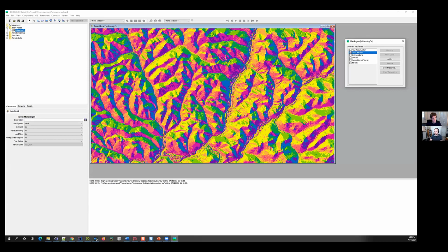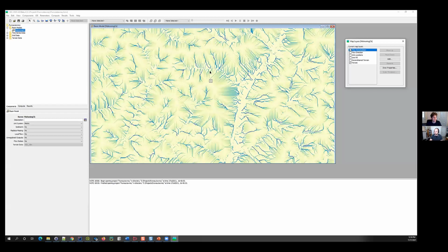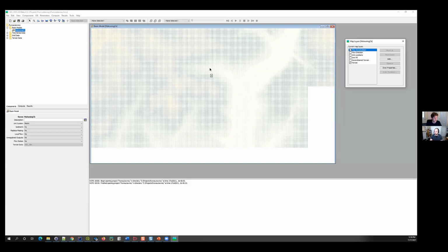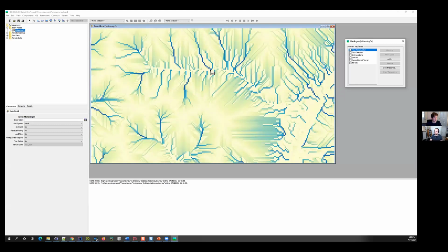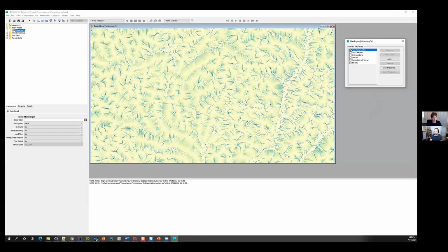And then if I look at the flow accumulation grid, it gives a notion of how many cells upstream of a particular cell flow to a given cell. So if I zoom in to say this cell, I can see there are 441 cells upstream. So that's the flow accumulation grid, and both the flow direction and flow accumulation grids help us with watershed delineations and characteristics computations. I will zoom back out.